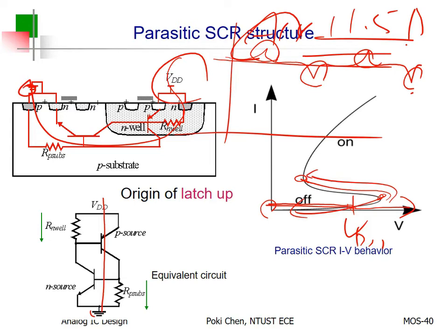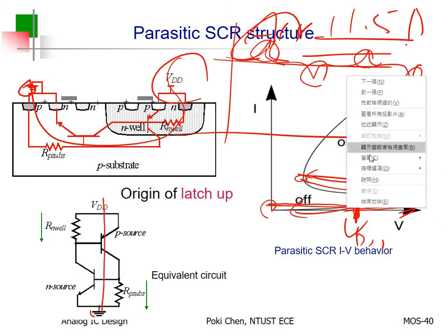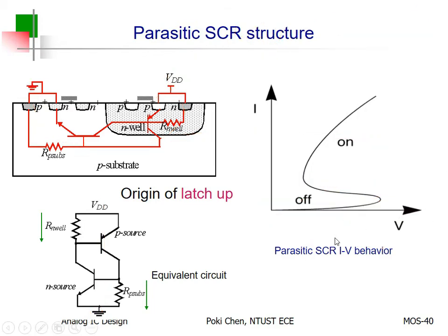So with your VDD here and too many spikes, it is more likely that you go up and then back to normal, right? The spikes go up and down, and unluckily it will more likely stay there. Then the leakage current is much, much higher than before, right?